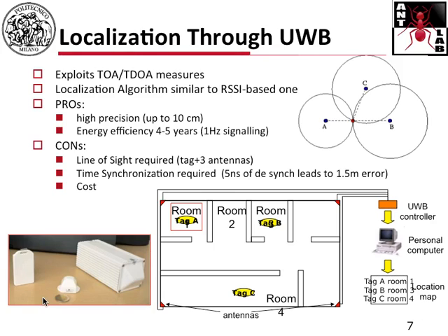The performance measure you see there, up to 10 centimeters of error, you can achieve if the anchor nodes and the client nodes are in line of sight. If they're not in line of sight, you go much higher than only 10 centimeters of error. Line of sight means that there's nothing solid in the middle.